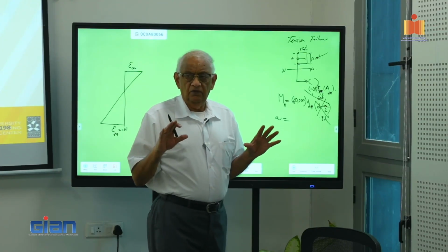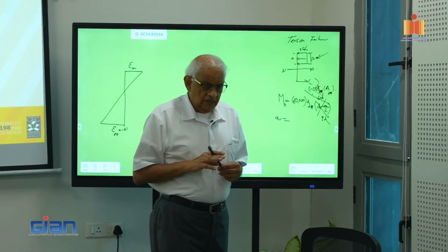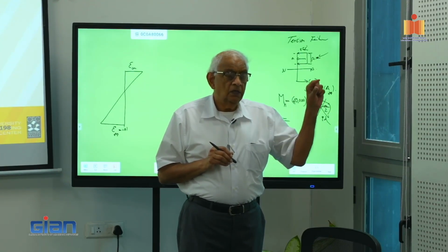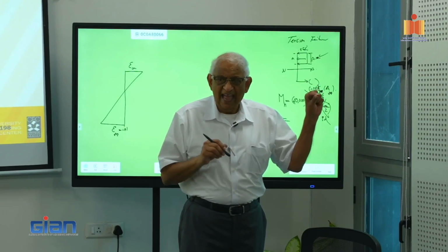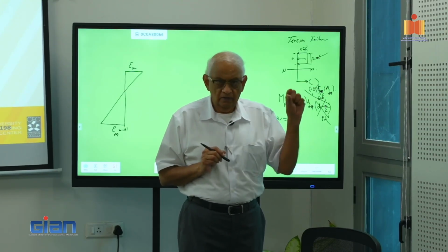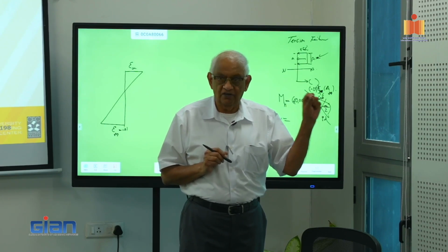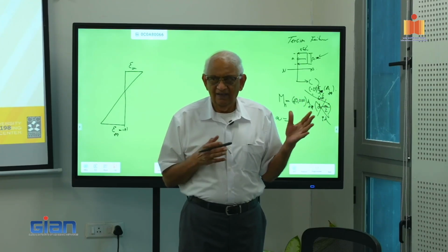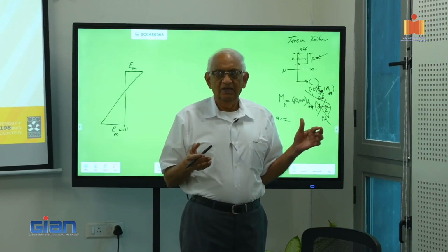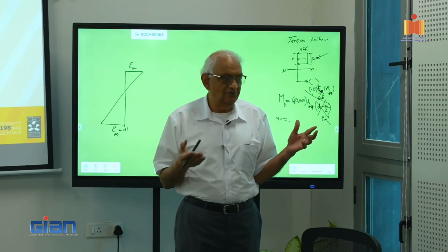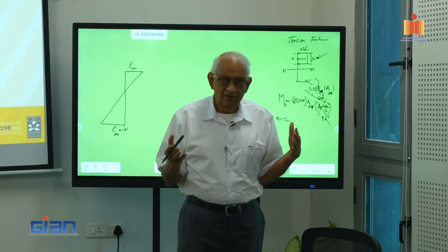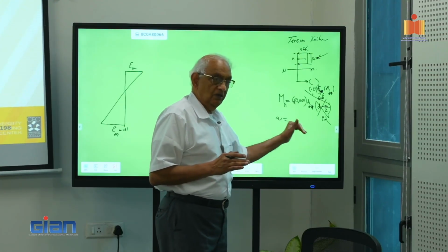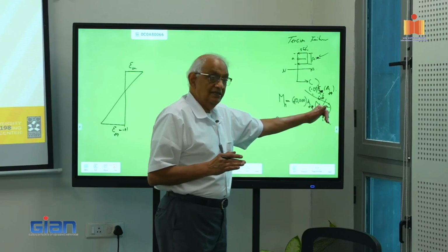I don't know how many of you observed it: in a tension failure, not compression failure, the depth of the neutral axis at failure, the uncracked part before it crushes, is about 8 to 10 percent. That's what people say. From a designer's point of view, remember, otherwise I would have to go through all the equilibrium aspects and then substitute it in here.